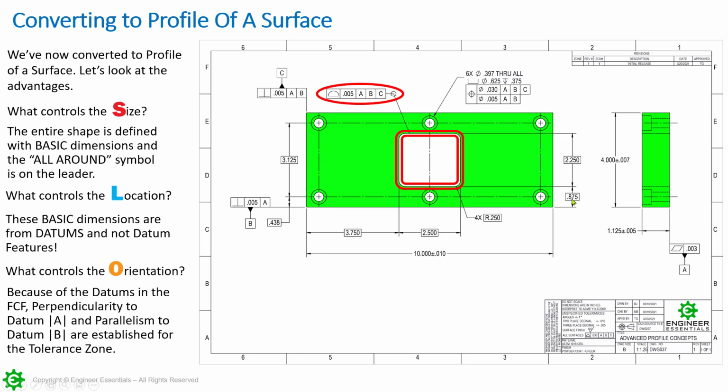The 7/8 over here is going to locate that from B. Now, side to side still open, right? We've covered orientation to A, perpendicularity. We've covered orientation to B, which is a parallelism or perpendicularity, take your pick. And then a location from B. Well, now we're oriented to B, which means that it's automatically perpendicular to C, right? And again, or parallel, take your pick. But it's not located yet from C.